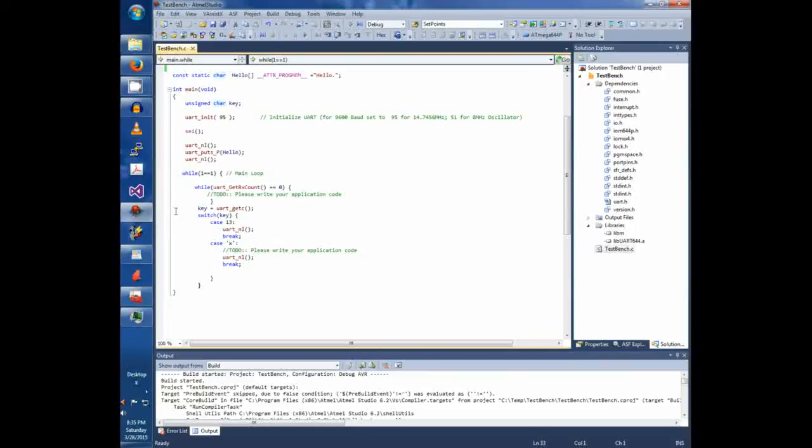When a key gets pressed, it will leave this loop temporarily, fetch the key from the keyboard, and use this switch function to determine what the key is and what action should be taken. With this, you can use single keystrokes as commands to test various functions, like retrieving the value of a variable from within your program, printing out port values, printing out register values, or just about anything you can think of.